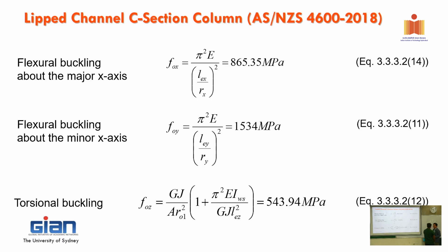Oh, good. Thanks. Because of the knocking in here, it actually reduced our effective length to half. So that one now is 1 meter. All right, so that's why you can plug into the equation here, it is 1000, and you get the buckling stress in here. And the torsional is when it's buckled in torsion. Right, so those are 3 pure failure modes of any single member subjected to compression.